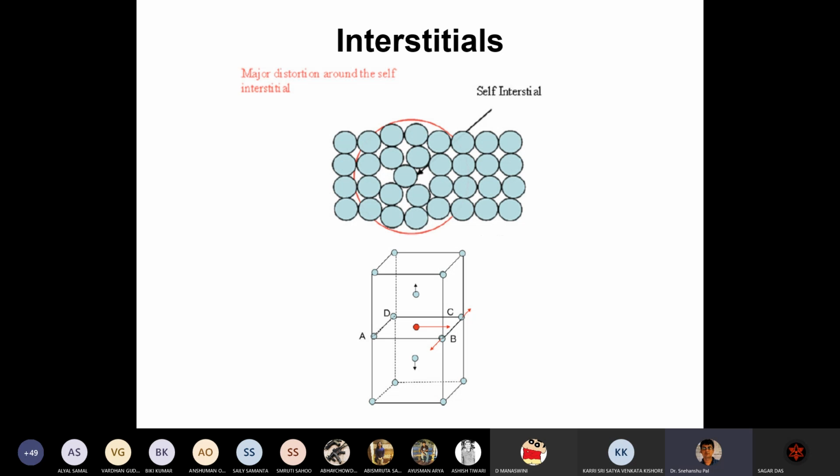As in a typical metallic lattice, the size of a void at interstitial position is small to accommodate a host atom displaced from a regular lattice point, and the corresponding formation energy is very high, and the concentration of self-interstitial in a pure metal or substitutional alloy is negligibly small if you compare them.